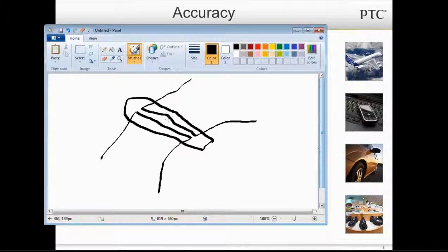And if you haven't noticed, for anybody out there that's a sheet metal guy, even now, the default accuracy that ProEngineer comes in is something called a relative accuracy, and they're starting to switch that now so that the sheet metal templates start out in something called absolute accuracy. I'll show you that as soon as we get back to our slides.